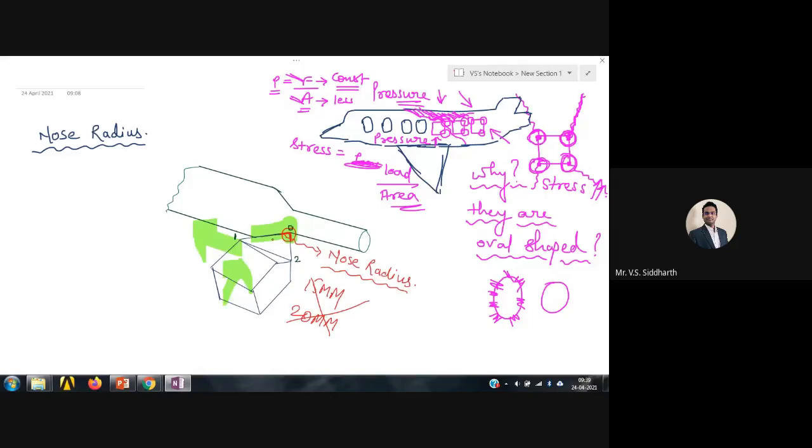It is not like that when you do the machining operation in the reverse direction, this O2 will become the major cutting edge. No, we will never do the machining in the reverse direction because this tool is supposed to be operated only in one direction. You can't do the cutting operation in the reverse direction. If you do that, then your surface finish will be completely deteriorated. You will get a workpiece which should be thrown into trash. You can't use it. Surface finish will be very, very bad. Okay. So I hope that you have understood this.